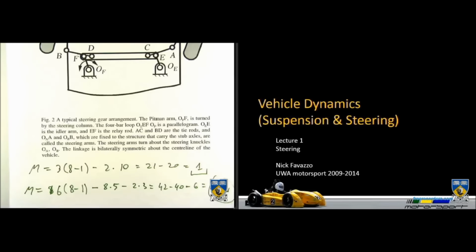Modern cars, as I said before, tend to use a linear input from the rack and pinion gearbox to convert the rotational input from your steering wheel. It eliminates links, so you're removing packaging constraints, a bit of compliance in the system, and weight. I've got some examples of alternate solutions as well coming up in my slides, so I won't go too much into that right now.